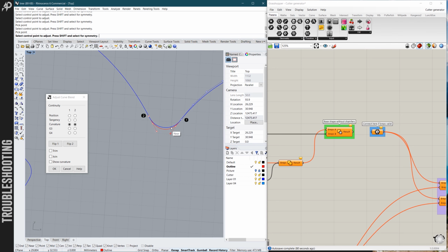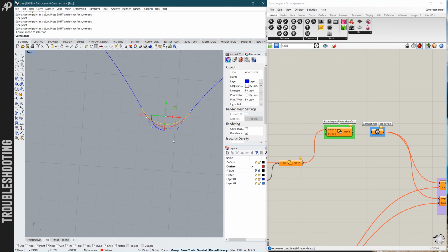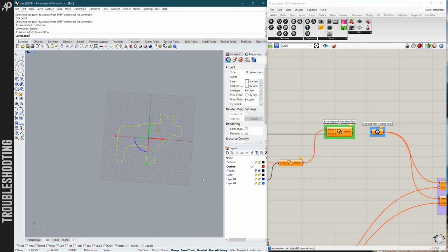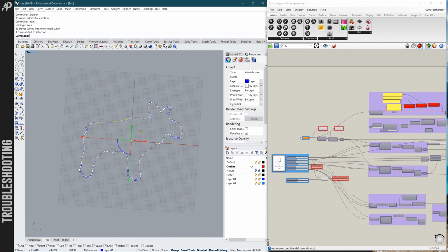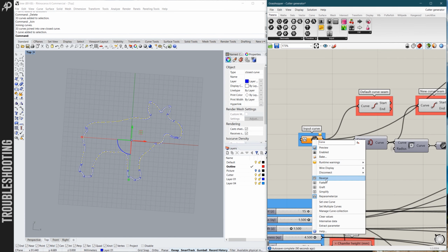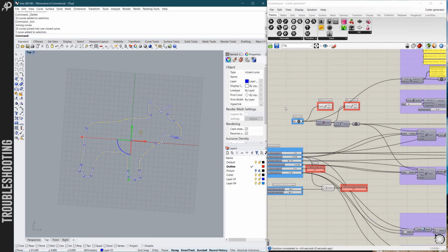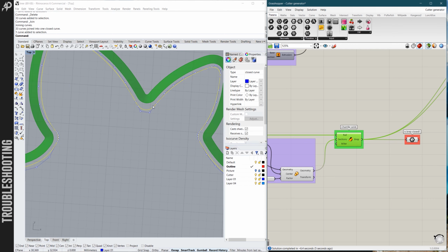And if we use this, it might solve our problem. Just OK. Now we delete the old arc, select everything, join again, reinsert to Grasshopper. Set one curve. Let it recompute. Check our surface. And now it's all okay.